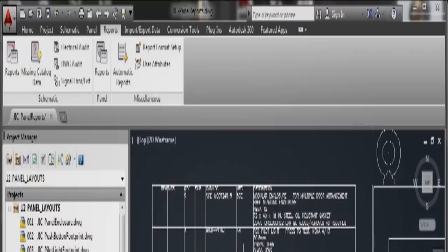And there you go. It was just some debris left over. Probably my graphics card being a little bit slow. But if you do see that happen, just type regen, R-E-G-E-N, and enter, and it will update the drawing. It's not something that's wrong with the drawing. It's just where the graphics card might have got a little bit confused because I panned when I was placing my report there. So there's my report for the entire project sitting on my drawing.